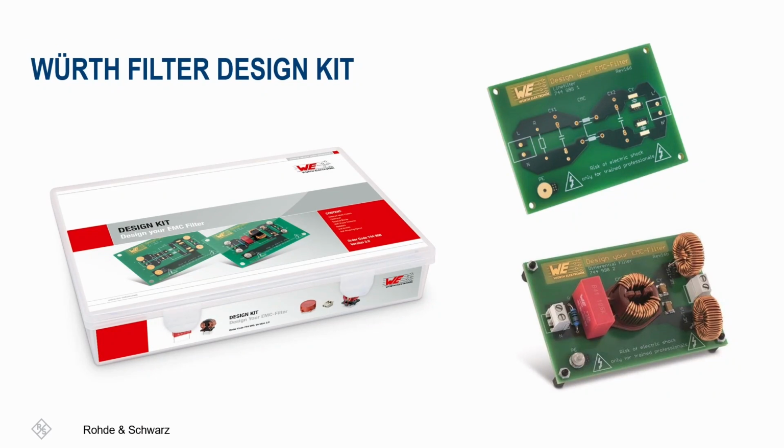It enables us to easily swap out components and determine which filter works best. Another reason why we did not experiment with common mode chokes is that the filter board typically requires soldering components in place, making it more convenient to use sockets for capacitors, but for the common mode chokes, it will be much more difficult.